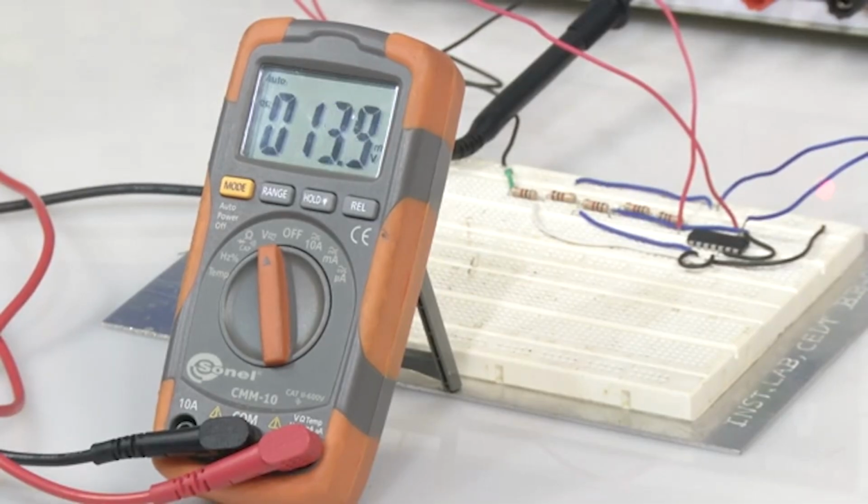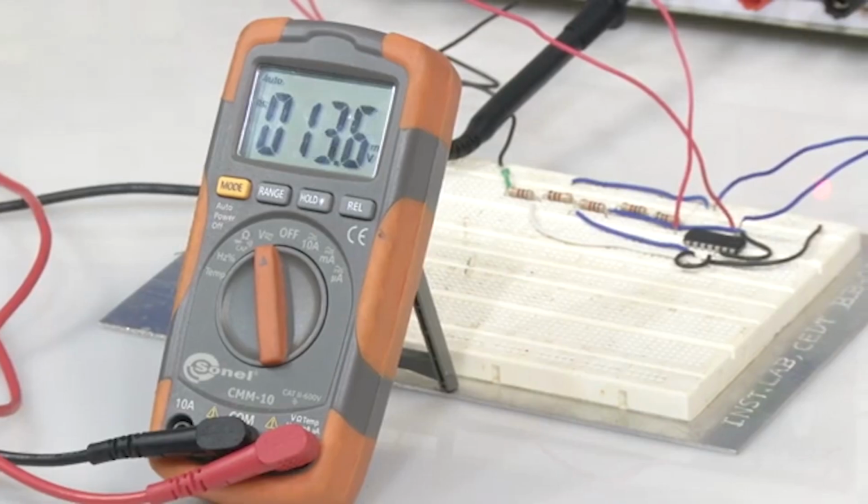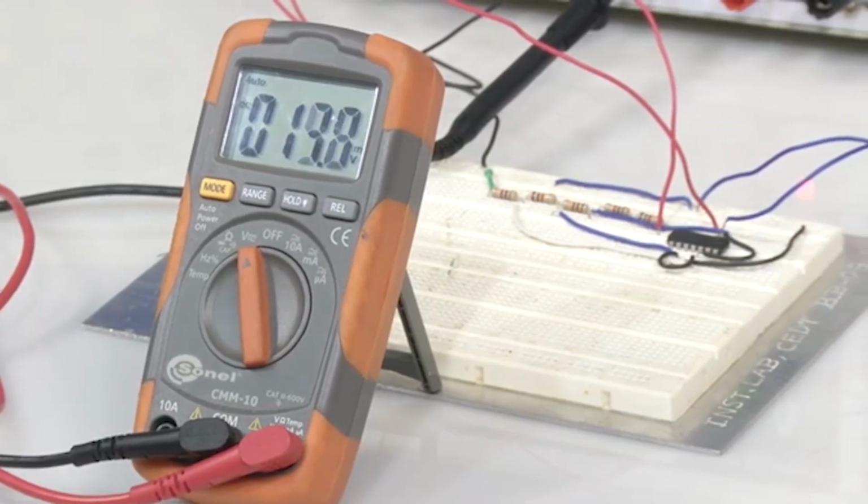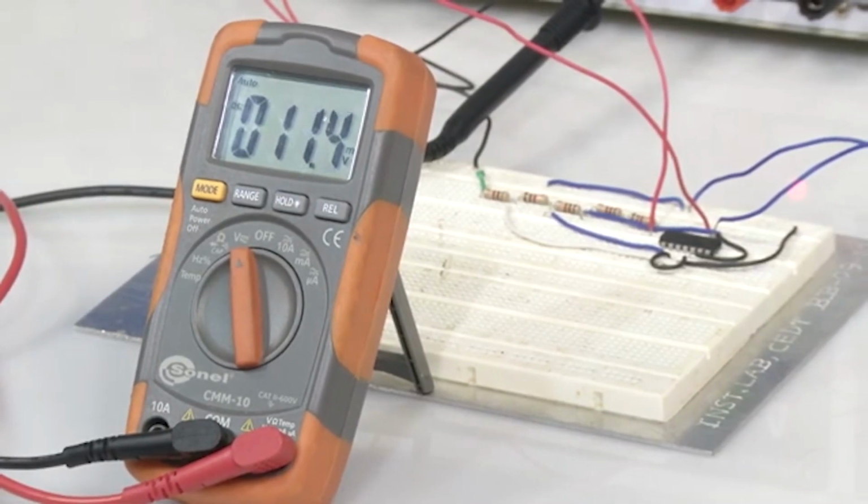So, when we represent it in digital way, it is nothing but 1, 1, 1. When we pass it through an encoder, input of encoder 1, 1, 1, the output of the encoder will be 1, 1. So, as a result we will get an output as 1, 1. So, that is how this flash type 2-bit ADC converter is working. So, I hope this is clear.